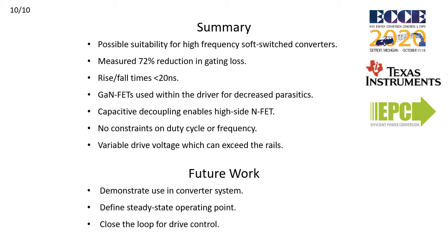Using 2 N-channel devices in its output stage, this design benefits from a significant decrease in parasitic loss relative to complementary CMOS output stages and acts to extend the efficacy of this design at higher switching frequencies. While generally used as primary switching elements, here 2 small gallium nitride devices further contribute to the driver's attainable switching frequency through their reduced parasitic capacitance.